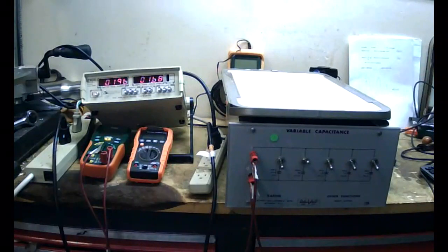And this is actually very practical, because if you go to a supplier and say, I need a 120 volt capacitor that will supply exactly 135 VARs, they're going to tell you we don't have that capacitor. We have probably 100 or 150 VARs, and you can choose from those.